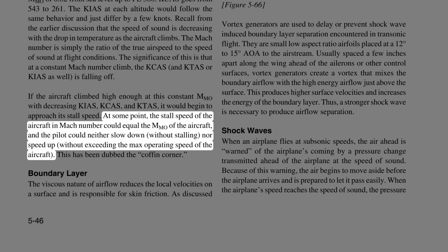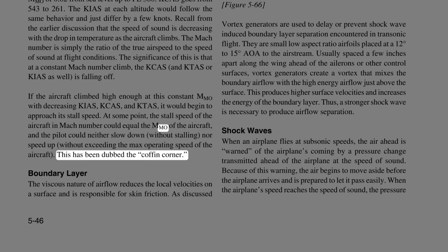At some point, the stall speed of the aircraft in Mach number could equal the Mach of the aircraft, and the pilot could neither slow down, without stalling, nor speed up, without exceeding the max operating speed of the aircraft. This has been dubbed the coffin corner.